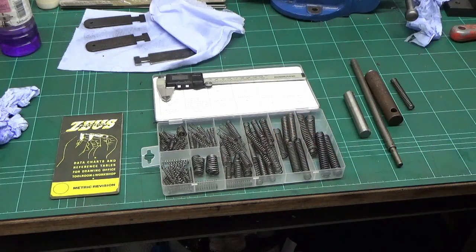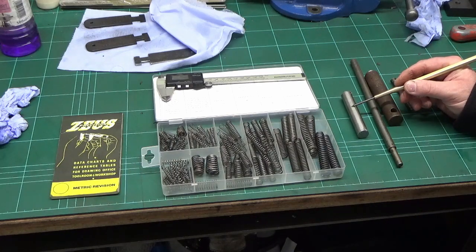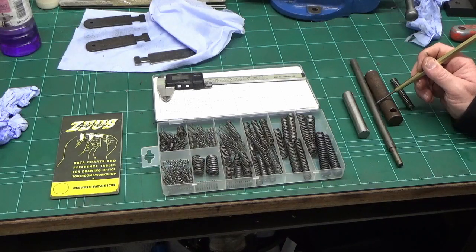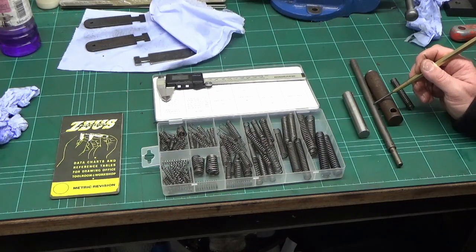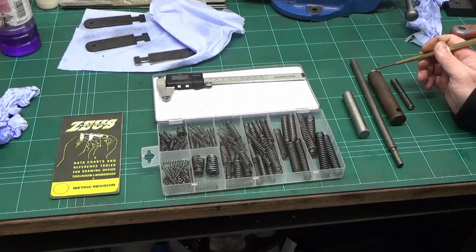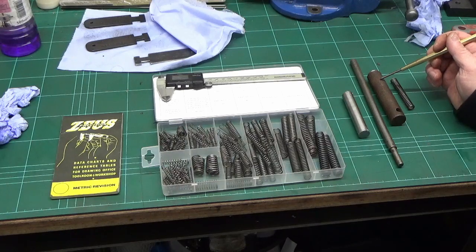And then from a materials perspective, we've got some 304 stainless steel, 16mm diameter, so that's going to make the main body. We've got some 17-4PH that's donkey's years old, which is a ferritic stainless, that's why there is some rust on it, and that's going to make the main pin, the double-ended pin. And we've got this bit of probably mild steel or something here, and that will make the other two parts, so the threaded end cap that goes in the end of here, and also the cone element that's going to hold the back end of the taps.